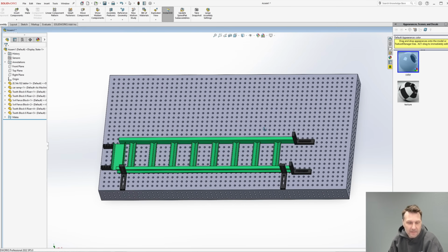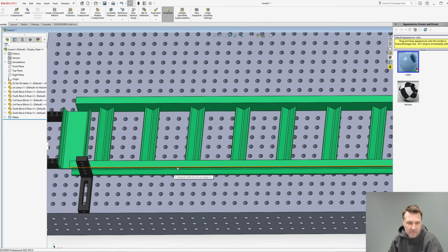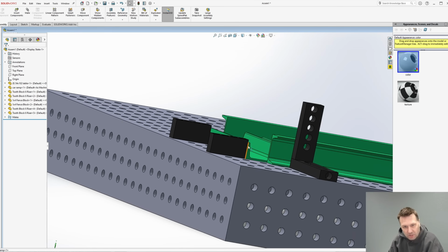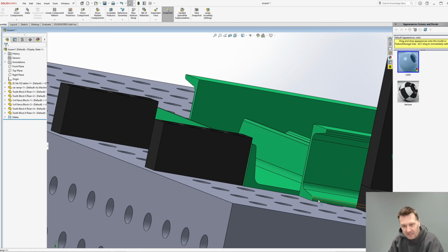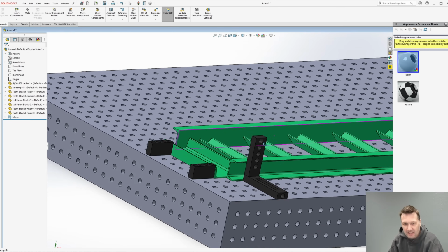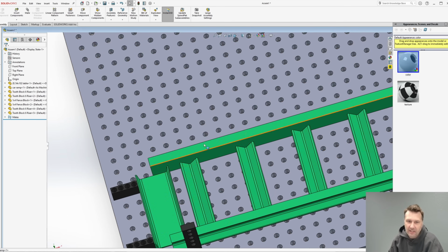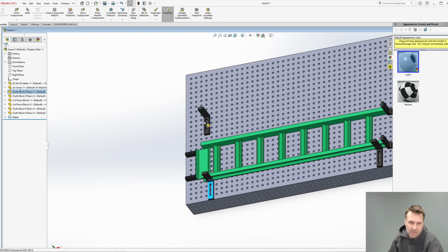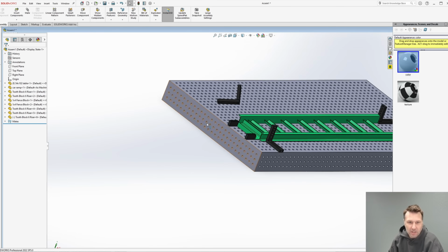I know we're at 15 inches from outside to outside, which we could use a fence block. But if you look at the fence block, see how it's short, right? And this is a piece of channel iron. We don't want this channel iron to roll. So that's why we're using the tall risers. But technically, we could use a fence block over here and it would land on 1 inch. But we want full control here. So we're just going to keep going with our tooth blocks here.